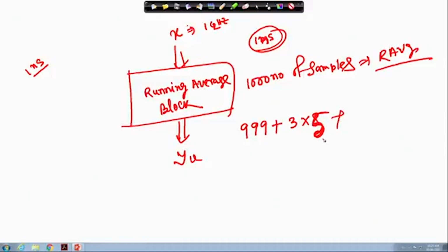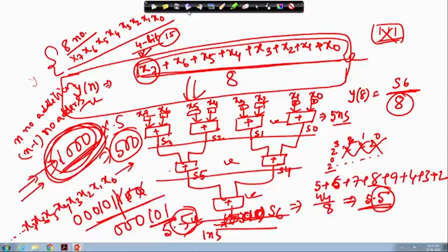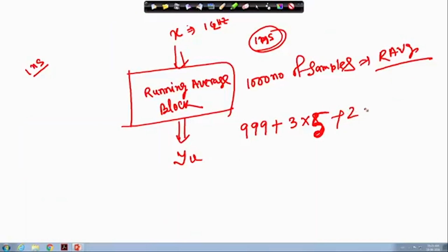What else is left is the delay for the input resistors and output resistors. Why two of them? I am using 8 at the input side and 1 at the output side, but the 8 are in parallel. Each consumes 1 nanosecond of delay, so the maximum is 1. I am considering 1 for the input delay and 1 for the output delay.